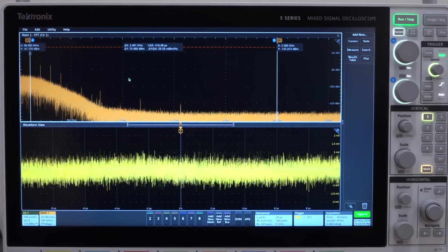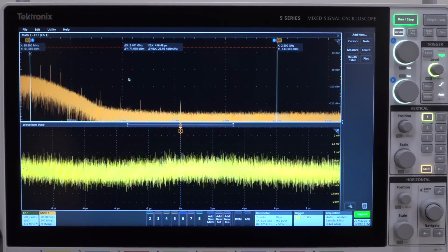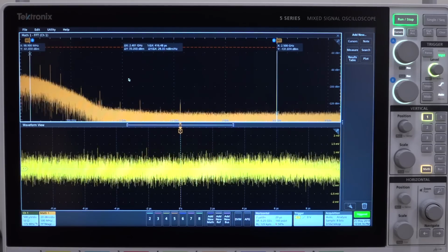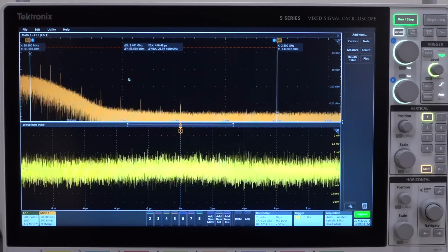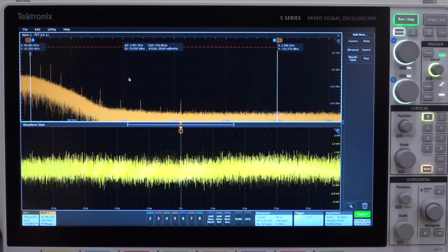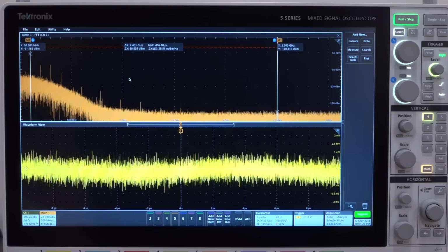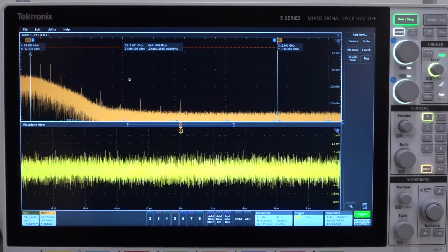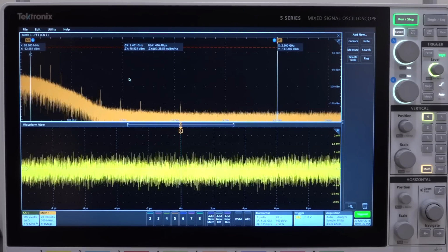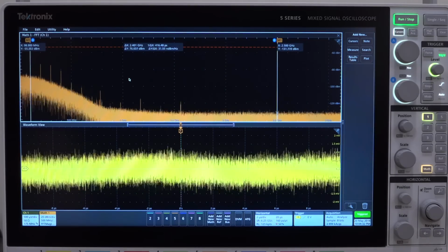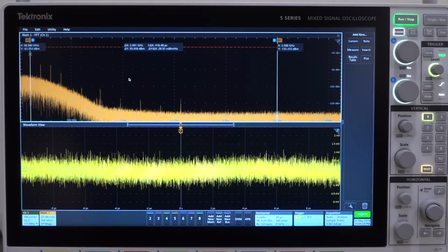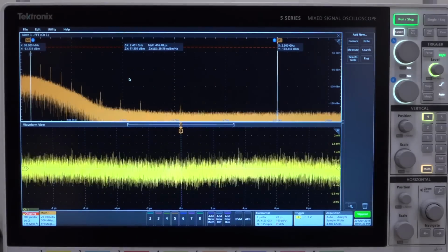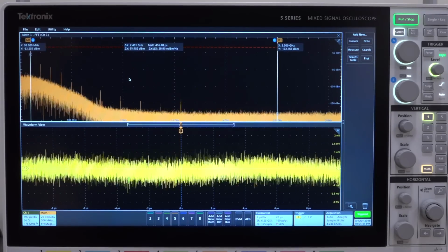Now one of the reasons why I can't completely null it out is that the amplitude accuracy of the arbitrary waveform generator in the millivolt divisions is a little bit limited. So for example, if I go to 1 millivolt changes, right now we're at 1.005 volt peak to peak. Now if I make it 4, I see no change. 3, as soon as I hit 3, I see a big change. So it looks like there are some discrete steps there that basically don't do anything, and only after a couple of millivolts do I see a change there.